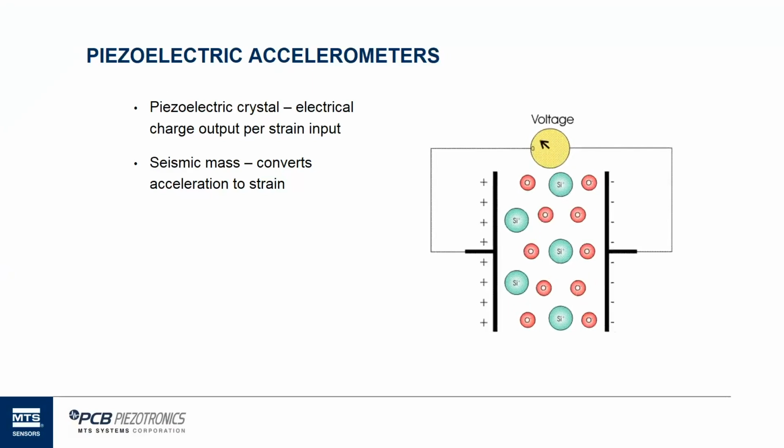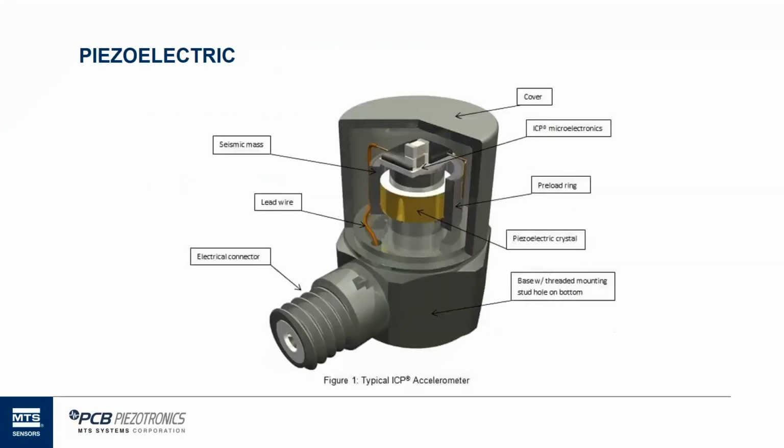So what it looks like, I'm getting more of an illustration type of diagram here, this is a piezoelectric accelerometer cutaway illustration. Most notably in the lower left-hand side, you see the electrical connector, and that's not multi-wire. You're going to get a coaxial type of connector, and when you look at that across the room, it's a pretty good bet that you've got a single axis piezoelectric accelerometer.